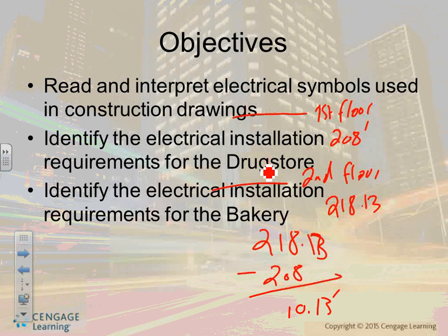Can you guys see the arrow? The arrow will point toward, in the upper right corner, you guys see a water heater with a disconnect? Upper right corner, okay. It says the home run on it is BS, which stands for Beauty Salon. Can you see that? BS is Beauty Salon, and 12-16. 12-16 is circuit 12, 14, 16.